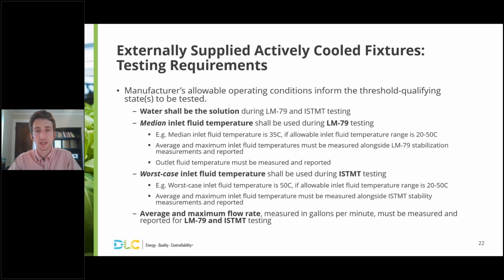For the LM79 testing, the median inlet fluid temperature should be maintained. So this median temperature is based on the minimum and maximum inlet fluid temperatures that I mentioned on the previous slide, and the median between those two. And then lastly, for the thermal tests, the worst case inlet fluid temperature should be used.